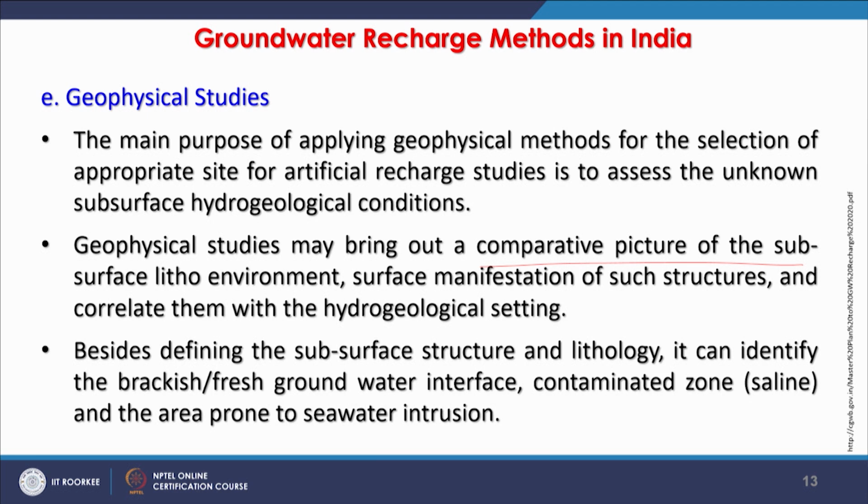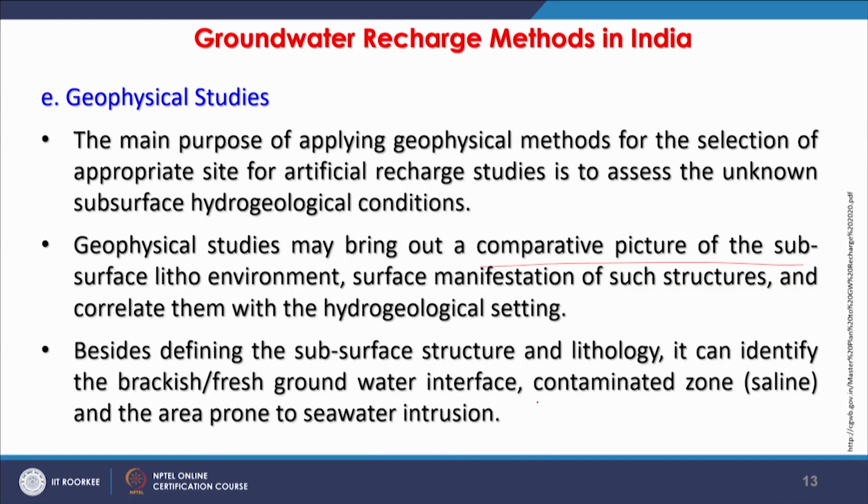Further, defining the subsurface structures and lithology, it can also identify the brackish or freshwater groundwater interface. So, geophysical studies are capable of identifying this. That can also help, and this is important in case somebody is going to have a recharge structure near sea areas or other places, or where contaminated zones or saline water are nearby. That is also very much required.